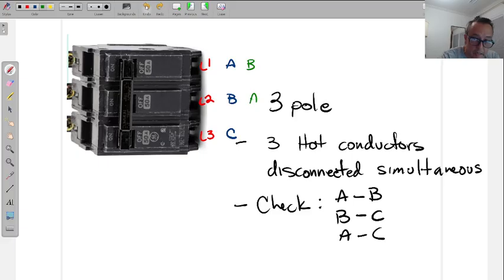Any combination would work. You can do C, B, A, that would work as well. So any one of the three combos, and then you can leave A alone and switch B and C. Either one is fine. And then you'd make the motor go opposite direction. Not forward or reverse, just opposite of whatever it was going.